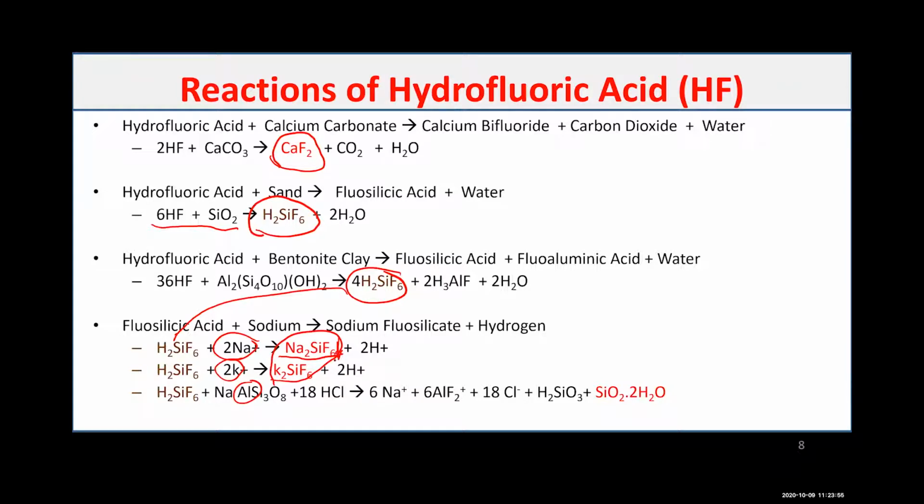The issue of the HF is that the reaction product will have a lot of precipitation. However, this precipitation doesn't happen immediately. It happens when the pH reaches 4 to 6. The reason for using the HCl is that HCl will not react with any of these. It will not react with the silica, it will not react with the bentonite, it will not react with any sodium clays or potassium clay or aluminum clay. It will stay in integrity and keep the pH at 0 all the time.